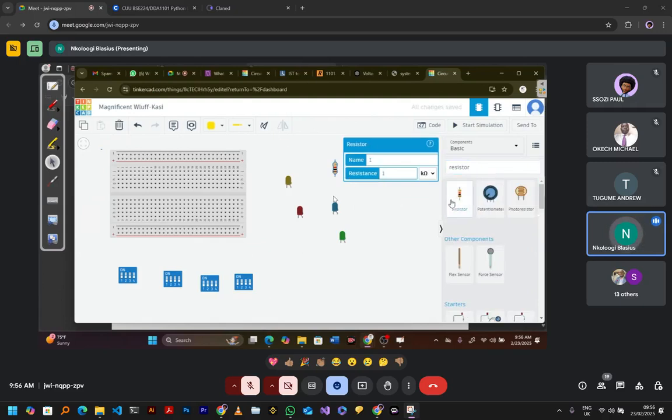So resistors, of course, first drag and drop 4 of them, then I show you how to change the values. Resistors have different values. The more the value, the more it is going to be limiting your current flow. So select any of those and then choose the value type. I'm not going to choose kilo ohms. I'll use just ohms. So the ohm is this, and then I write here 330. You see when it changes the color codes.